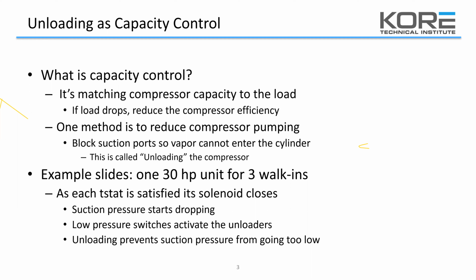So we're going to look at some slides here that would be an example for just like a 30 horse, a big 6-cylinder compressor, where we have 3 walk-ins, and as each, you'll see in a minute in the animation, as each thermostat is satisfied, we drop out a portion of the compressor to maintain its ability to pump the amount of refrigerant necessary to maintain the load.